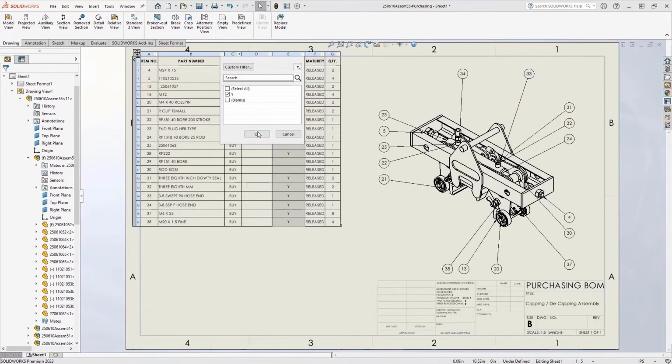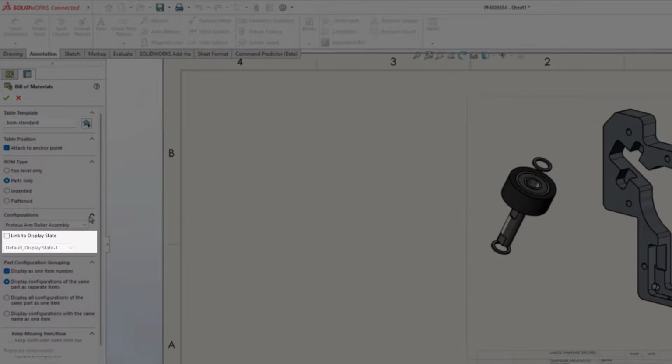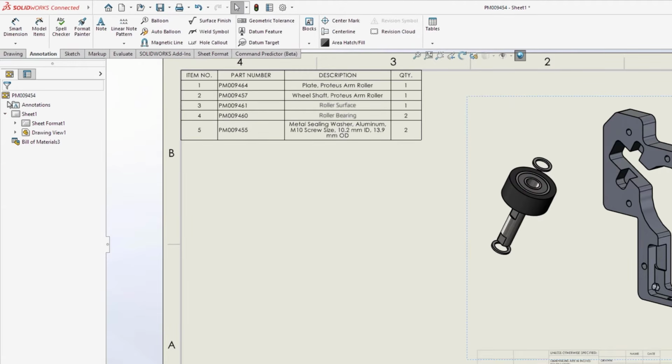Another more recent example, if I can cheat here and add another, is that you can also now filter BOM visibility based on model display states inside of SOLIDWORKS Design. So if you're looking to limit model overhead, which helps for performance in terms of your PC's resources, this is another path that SOLIDWORKS users have taken advantage of in recent years.